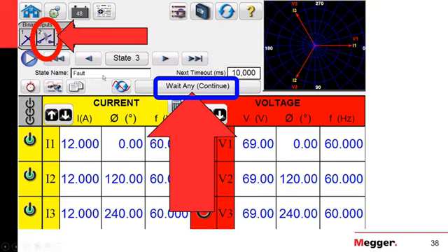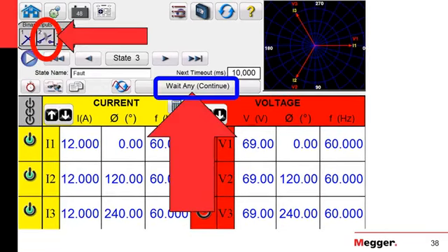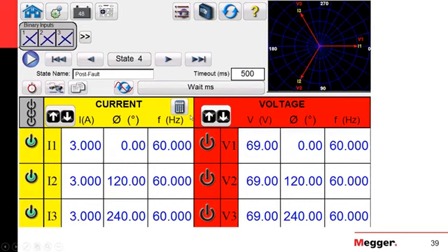Since we are expecting the relay to trip, we are going to program binary input number 2 in the test set to listen to that output from the relay. And we're going to say that once it trips, it goes into the next state, which could be my post-fault state of 3 amps, or I could say 0 amps. In this case, I should have programmed 0 amps, not 3. Anyway, the post-fault state is one you consider a good condition operation. Since there was a trip in the breaker and there's nothing else, it should have been 0. I'm sorry about that.